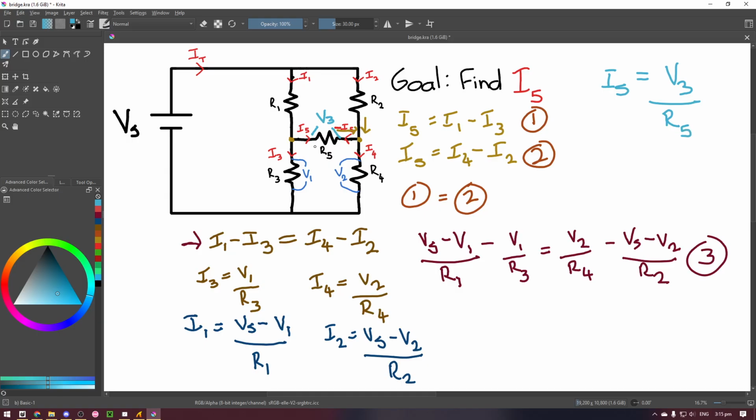We can use Kirchhoff's voltage law around this loop, clockwise, with V3 going this way, which is positive, as I've done the current going that way. So we'll have V3 plus V2, as it's positive again, minus V1 equals 0.